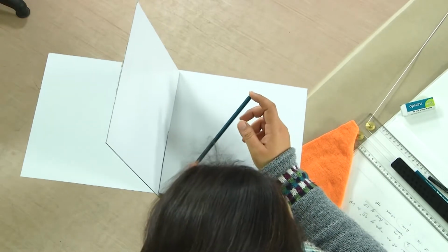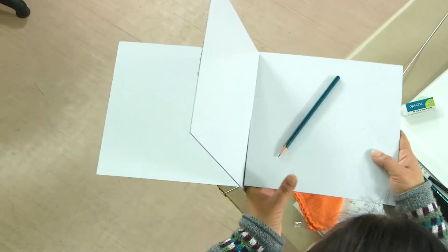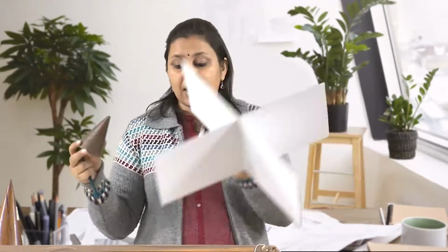If you essentially see, if it is inclined to one plane and we want to incline it to the other plane, we are moving it in a cone-like manner. So, let us understand this with the help of a cone. The movement is like that of a cone. Suppose there was a line which was making an angle of, say, 45 degrees and now it has to make an angle of 45 degrees with VP as well. We will only raise it in such a manner that it starts to make an angle which is like a cone. So, what happens with the cone?